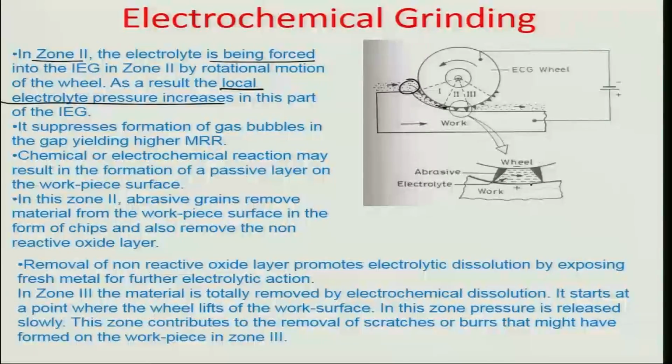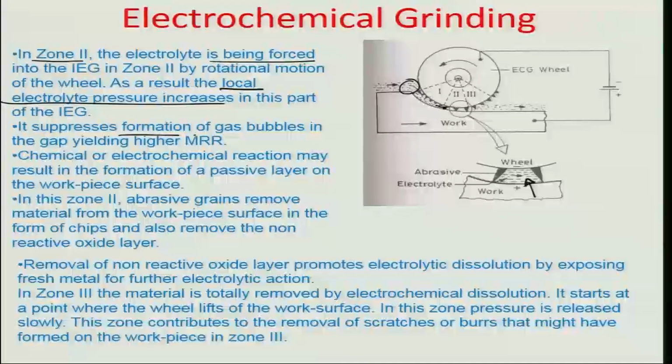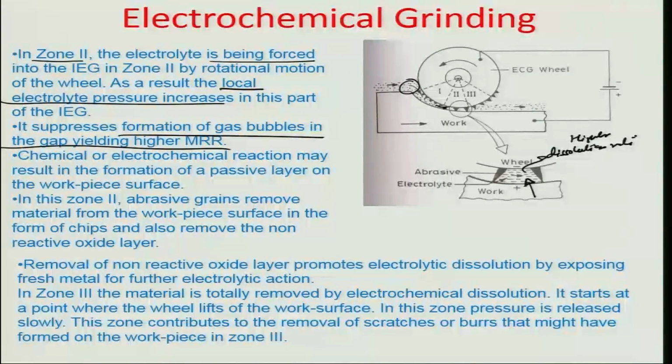One thing which is interesting in this case is that because of a self increase in the pressure value, the dissolution levels of the hydrogen may reduce because it may simply outgas the hydrogen. So it suppresses the formation of gas bubbles in this gap, and that may result in a higher dissolution rate sometimes in this zone 2. So there is a high dissolution rate, and there is also a mechanical action in zone 2.